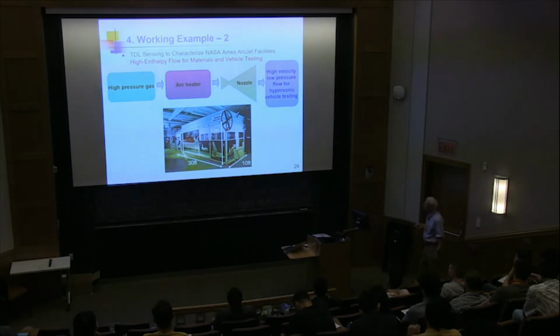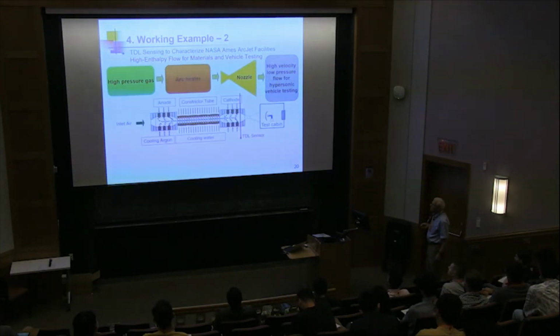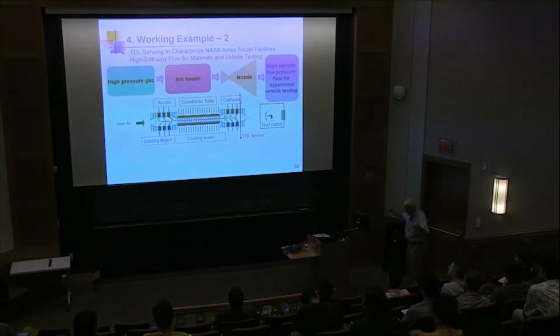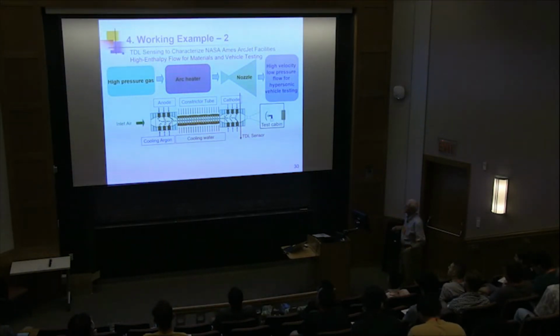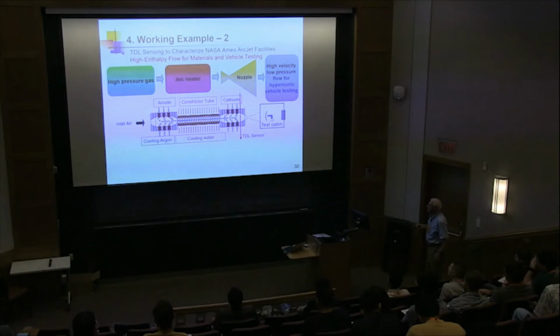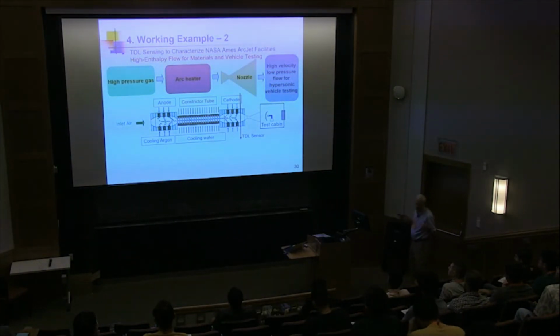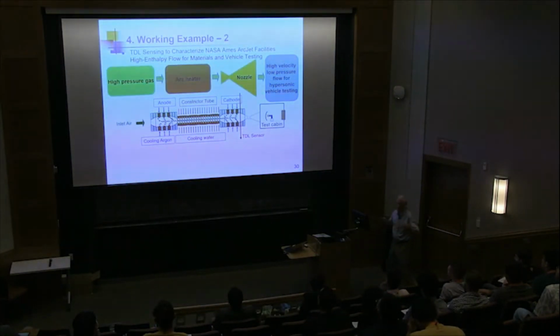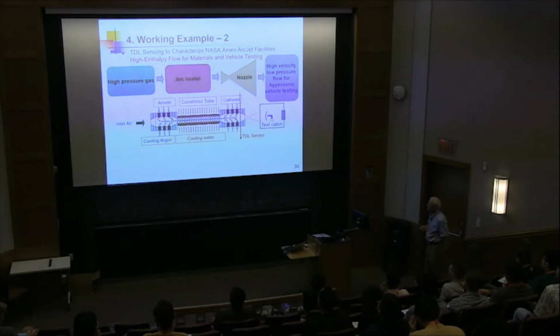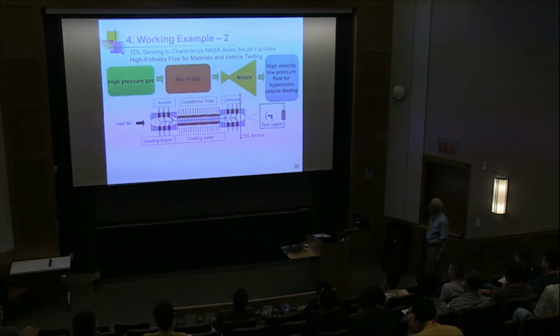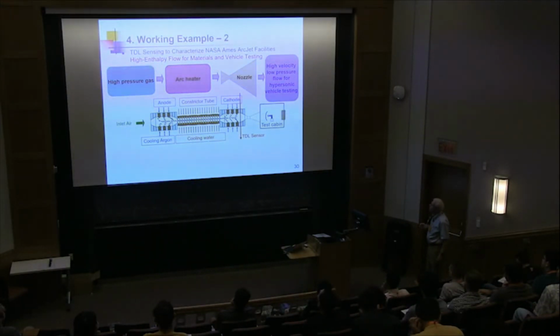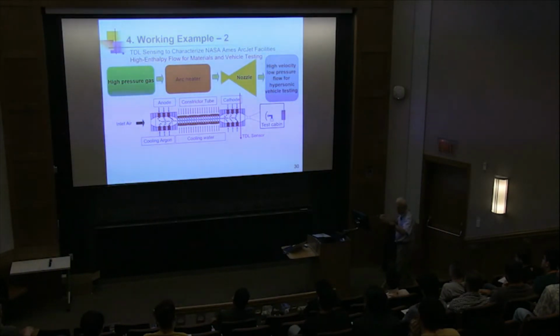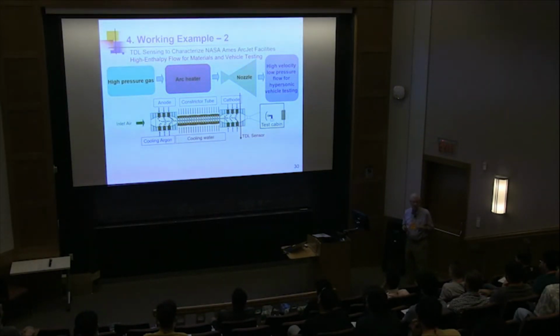They put this thing in kind of a big box, might be 30 feet by 10 feet. It's an axial discharge called a constricted arc. And so there's an anode and a cathode and heavy-duty water cooling because there's a lot of losses. So the thing looks like a giant nest of water tubes and pipes. And they'll use this to heat air, which they then accelerate. This basically builds up the stagnation enthalpy, expands it into a nozzle, creates high velocities and temperature, and tests shuttle tile materials. It's thermal testing.